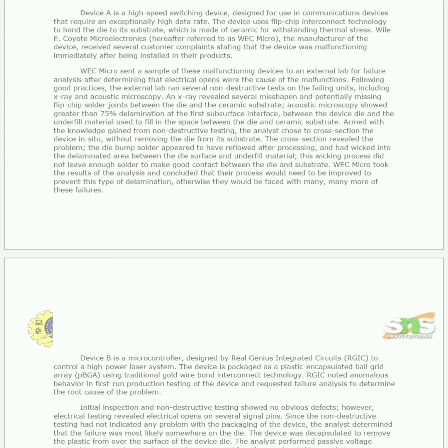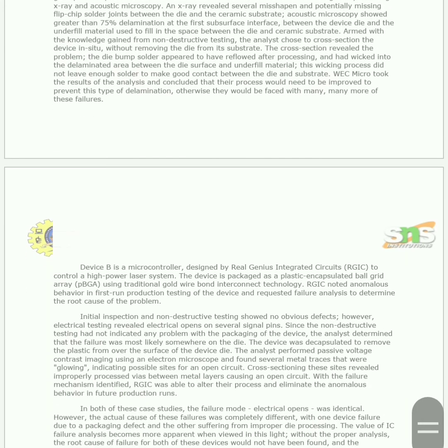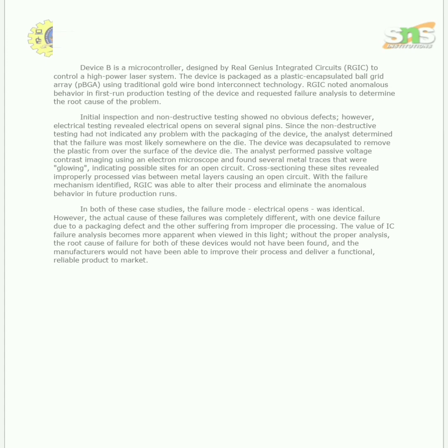In both of these case studies, the failure mode, electrical opens, was identical. However, the actual cause of these failures was completely different, with one device failing due to a packaging defect and the other suffering from improper die processing. The value of IC failure analysis becomes more apparent when viewed in this light. Without a proper analysis, the root cause of failure for both of these devices would not have been found, and the manufacturers would not have been able to improve their process and deliver a functional, reliable product to market.